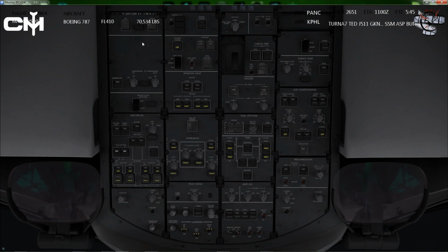Now this is one of the things they said, you can't do anything with flight control switches, so don't even cover it. So okay, that's a fair point. Moving down, however, the heading reference switch needs to be normal, this guy here. The primary flight computer's disconnect switch needs to have the guards closed. This light needs to be out.